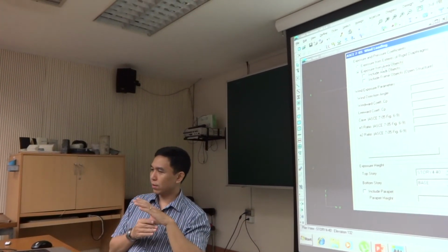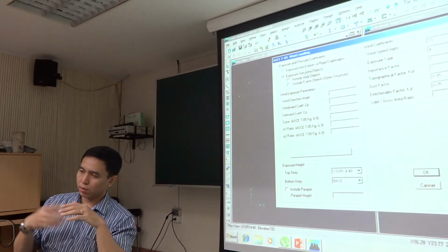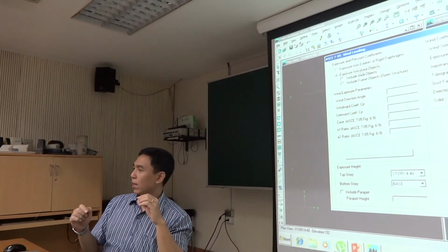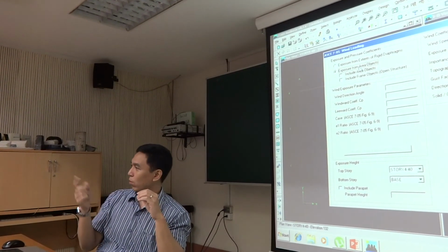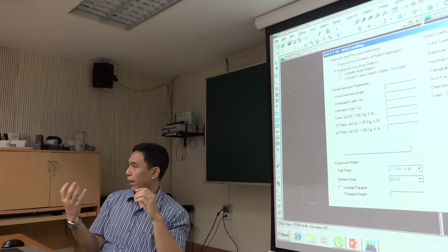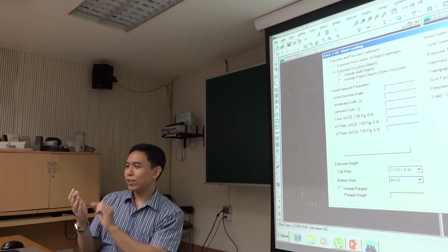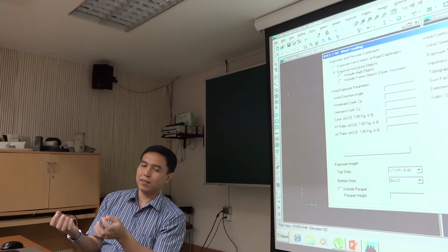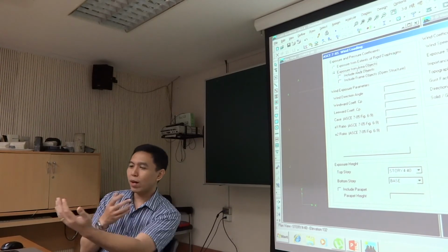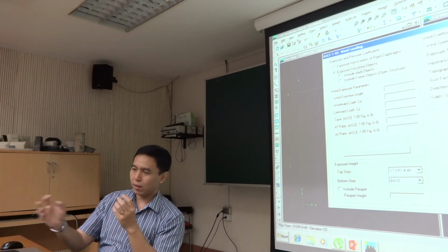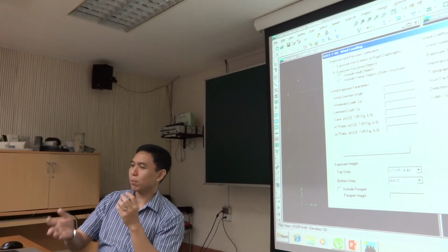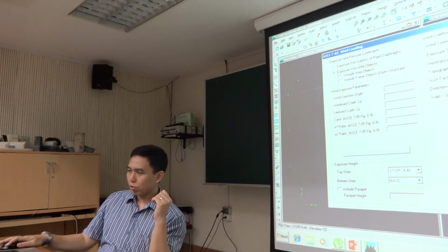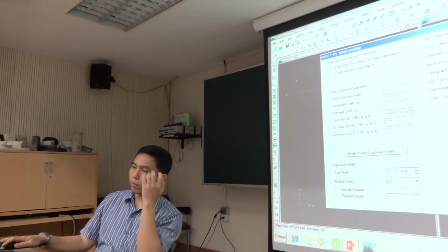and then apply the pressure coefficient on that wall. That one is more complicated and more work. You have to draw not only the structural walls, you have to draw the exterior envelope of the building and apply the pressure coefficient for each element. So it is tedious and it can cause mistakes. If you make a mistake with the positive and negative sign for the leeward and windward sides in the pressure coefficient, the force will be wrong. So I suggest you use exposure from rigid diaphragms.